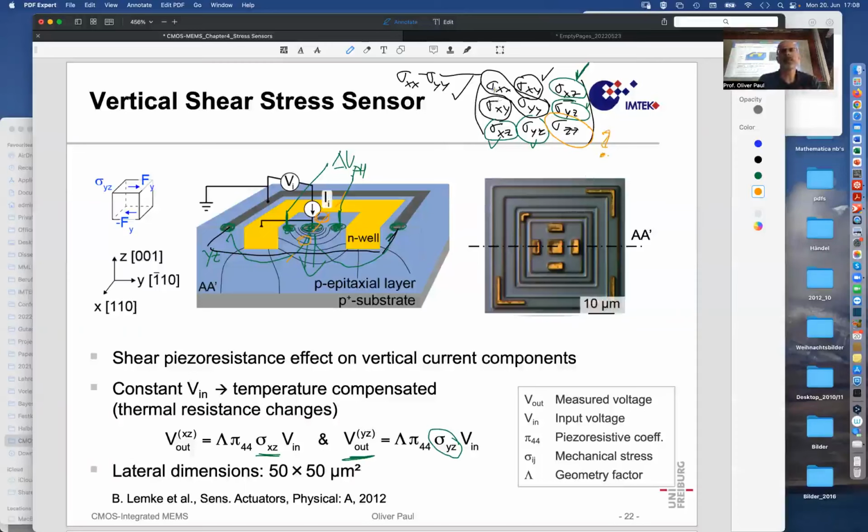Just as it is difficult to measure, it's actually impossible to measure these stresses sigma XX and sigma YY separately. With piezoresistive sensors, you cannot separate those. And I mean, we have done enough thinking, and there are reasons to believe, not only to believe, to know that actually you can't separate them. Sigma XY is also a combination of a longitudinal stress and a compressive perpendicular stress.